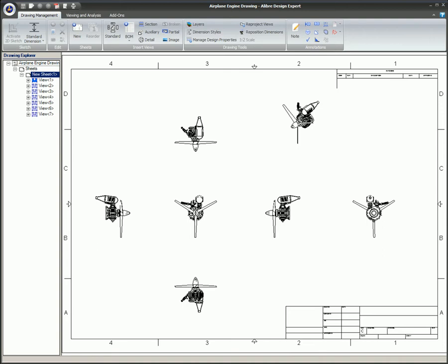Since the drawing uses the model's geometry to generate the view and does not project the edges, fast views will not be exported to DWG or DXF file formats. If you do not have an adequate video card, you will not be able to utilize fast views. Any video card purchased within the last 5 years should be able to correctly display these views. However, if you do have an older video card that does not support fast views, verify that you have the proper version of DirectX installed, as well as the latest video card drivers installed. If you still have issues, this option will have to be manually switched from enabled to disabled.